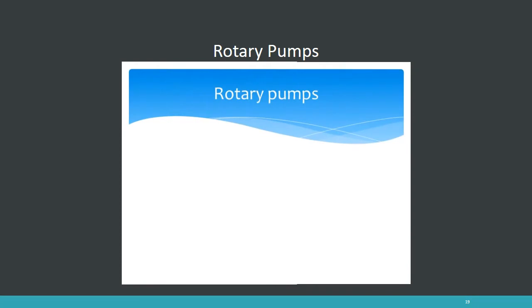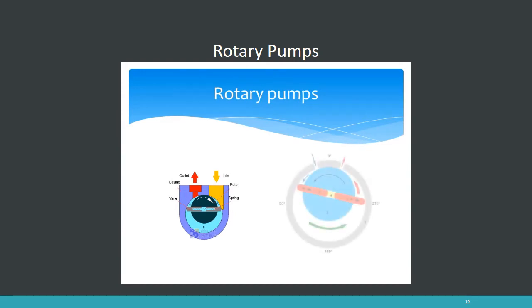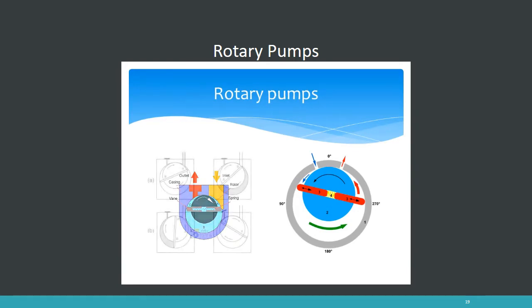The following video will explain how rotary pumps work. Rotary pumps are defined as being vane, piston, flexible member, lobe, gear, circumferential piston, or screw pumps. In all of the rotary designs, the chamber is created progressively through rotation of the drive shaft. There may be one or more chambers open per revolution depending on the design.